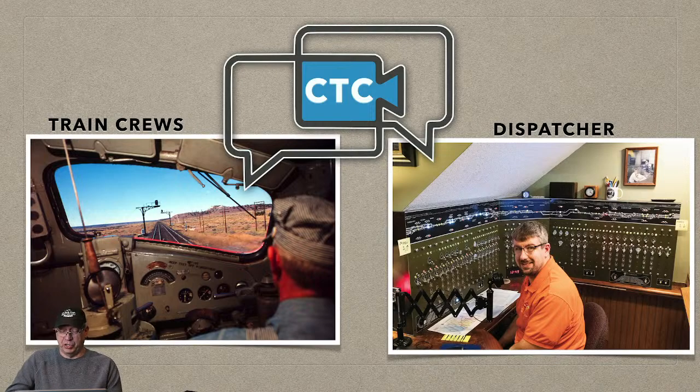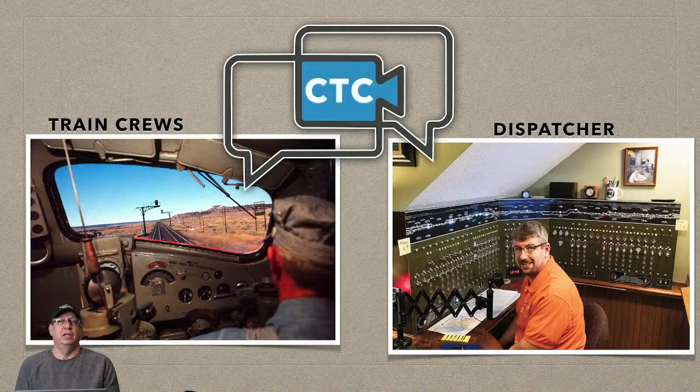There's also an awful lot of safety features built into the CTC panel. You cannot line two trains onto the same track. Physically or electronically, the system will not allow you to tell two trains to occupy the same track. Also, you can't run trains the wrong way through a switch. If you're trailing point through a switch and you're on the main and the reverse route is lined, you will get a red signal there, and the dispatcher cannot line you through that turnout until the route is set to normal, and the panel lets the dispatcher know this.